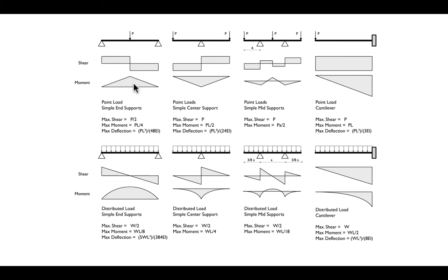If you look at the moment diagram, though, you realize that we're going to be giving up a lot of weight if we simply select a regular steel beam, a regular W shape, because we don't need as much depth or we don't need as much area. We don't need as much section modulus, if you want to be really accurate about it, at the ends as we do in the middle. The middle is where we need the greatest depth, the greatest amount of material farthest away from the neutral axis. And so ideally, we would like to design a triangular beam for that situation.